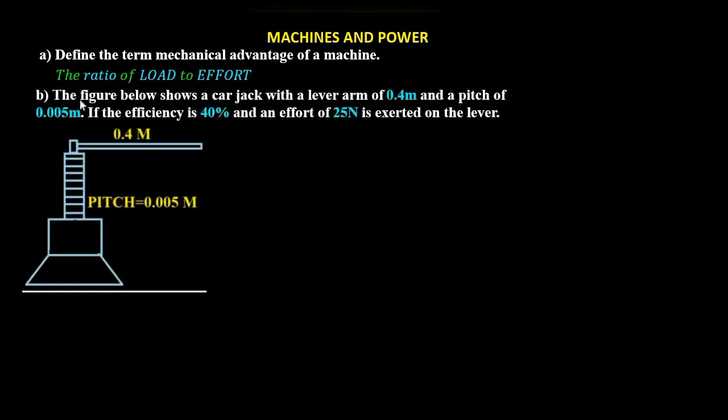Then part B, the figure below shows a car jack with a lever arm of 0.4 meters and a pitch of 0.005 meters. If the efficiency is 40% and an effort of 25 newtons is exerted on the lever, then Roman 1, determine the maximum load that can be raised.